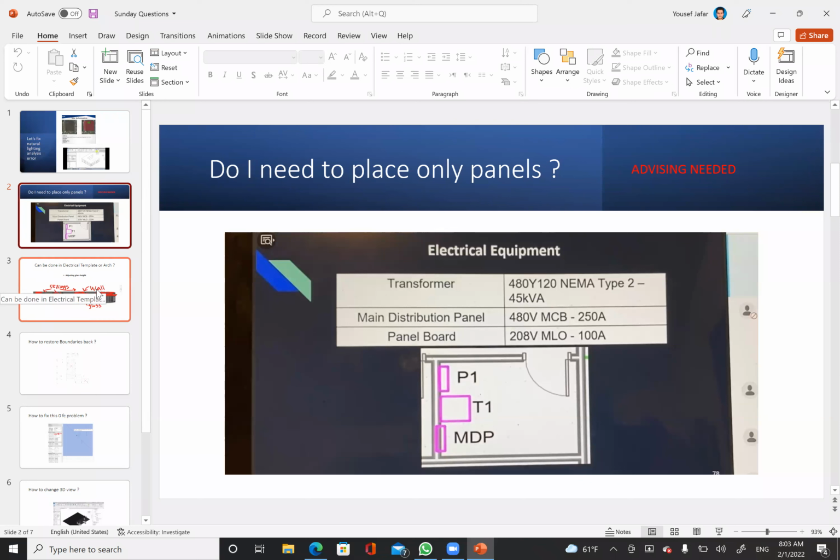Generally, if there are multiple panel boards, there is going to be one MDB, because individually each space should have a breaker board, so that all the accessories in that vicinity can be controlled.